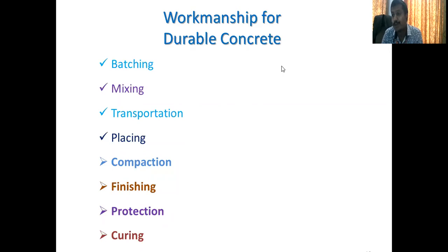So how are you going to take this weight? Batching is nothing but the process of taking measurements to prepare that concrete. Whatever the ingredients of the concrete, to make it in a fixed proportion, you are going to measure the material. 1 kg cement, 2 kg sand, 3 kg aggregate. This process of measuring is nothing but batching. Weigh batching and volume batching are the two types.